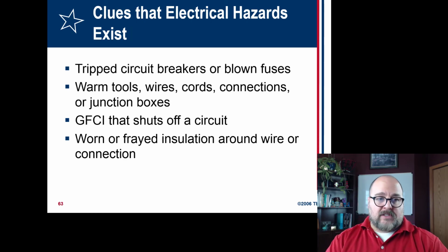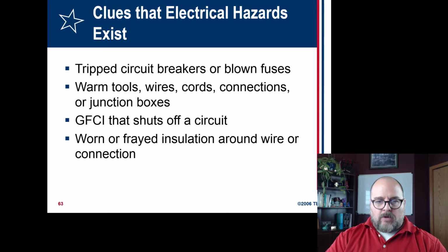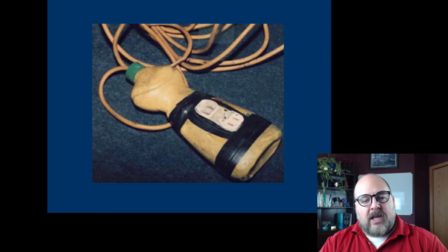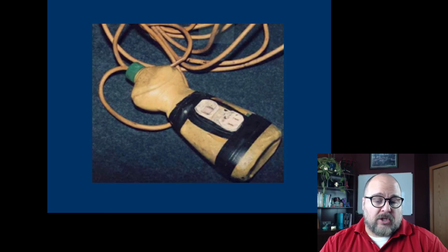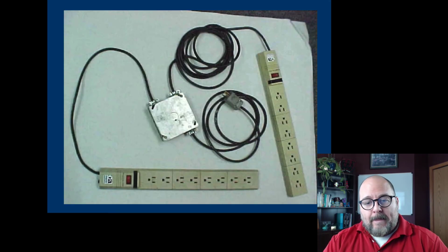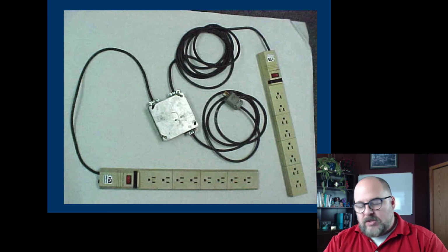Clues that electrical hazards exist: tripped circuits, blown fuses, warm tools, wires, and I've done that before too. A GFCI that shuts off a circuit, worn or frayed insulation. These are all problems. Somebody got creative and they used what looks to be a dish soap bottle, turned it into a box. Can't do that. It's not designed for it. Here, someone tried to get cute and they used a junction box to service two different multi-outlets. You can't do that.